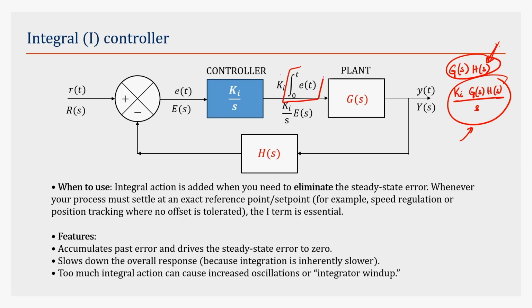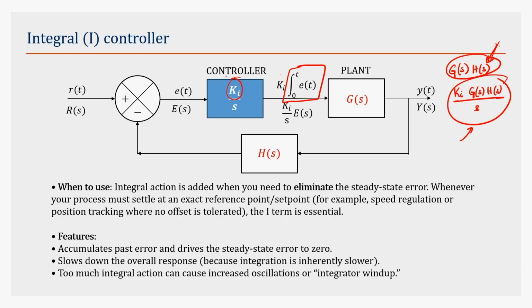What is important is that it is an integration of the error signal, which means it is not just looking at the error signal at that particular time instant, it is looking at the error signal from the previous time also, from 0 till the present time, and then it is summing it over or integrating it, and then the action taken by the controller is on that quantity, not on the error signal at that particular instant.